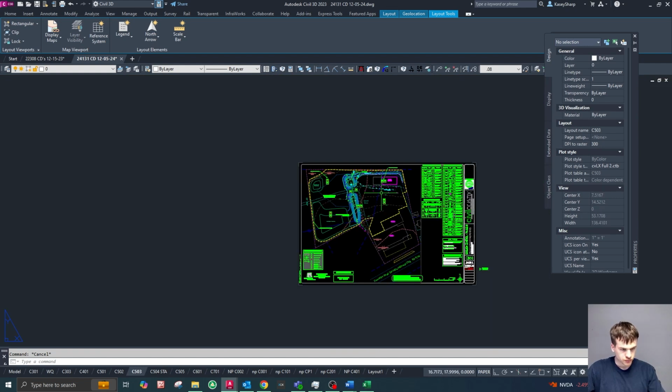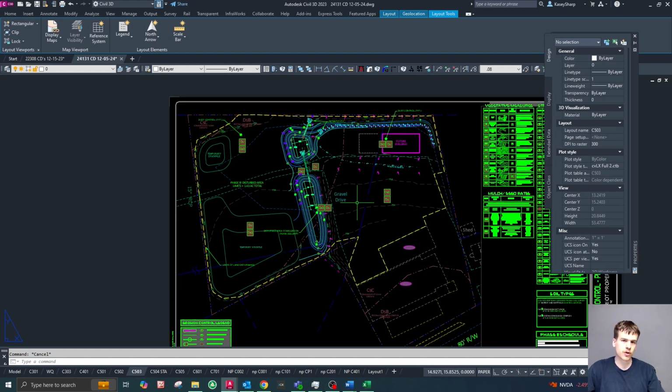Okay, so the contractor is going to take our erosion control plans, and at each step, or in 3 different phases as construction continues, they'll be adding, changing, and removing different best management practices, all while they're building the stormwater facilities, erecting a building, and doing any type of construction that's going on site. They're also employing these best management practices to prevent excessive erosion.